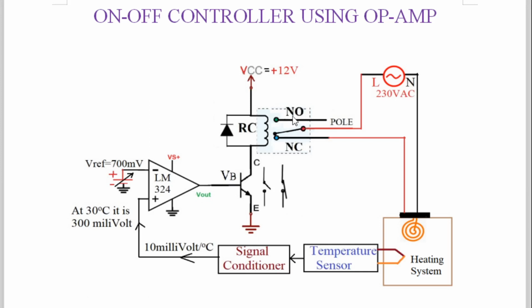as soon as the relay coil gets magnetized, your pole will get connected to NO, and therefore NO becomes NC. This NO terminal, you see, is not connected anywhere. So as soon as the pole is thrown to the NO position, NC becomes NO and NO becomes NC. Here the AC mains live voltage 230 volt now gets disconnected, because the pole is thrown to that side and the live terminal will not be applied to the heater.